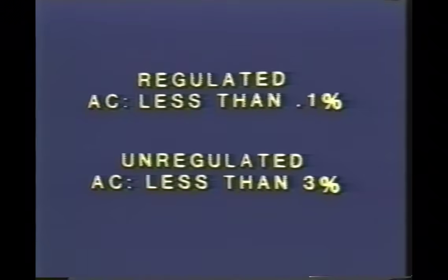However, if you start to get up around 5% ripple, chances are pretty good your capacitor is starting to fail, so keep an eye on it. I try to use about 3% as the figure, and if it goes over 3%, I usually change the filter capacitor.